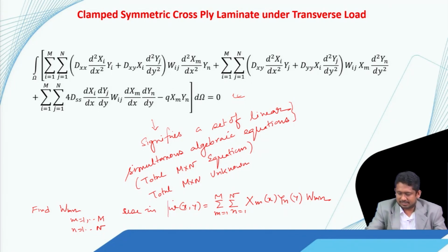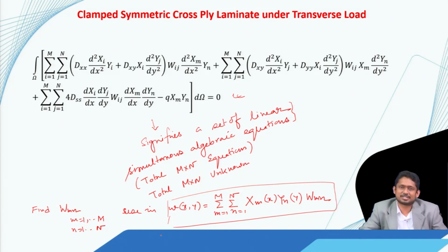So, this completes this solution, and again because this laminate was symmetric, we could separately solve the third equation, that means the out of plane equation. If the laminate was not symmetric, we would have to solve all the three equations. In that case, we would get more number of equations and we have to solve them simultaneously.